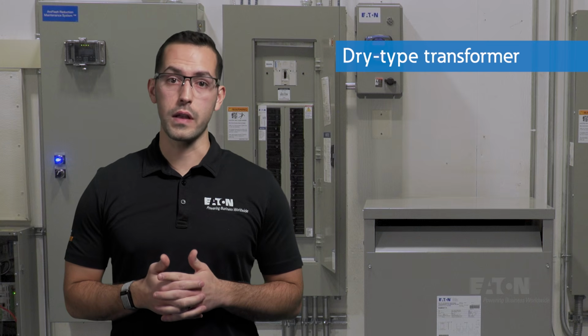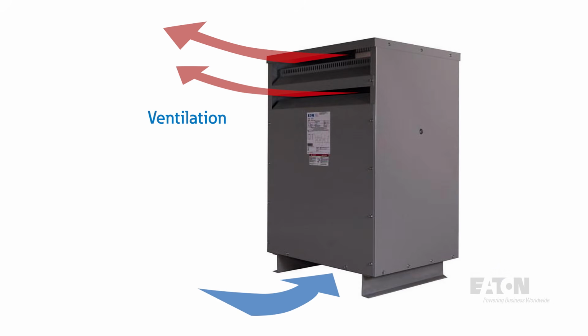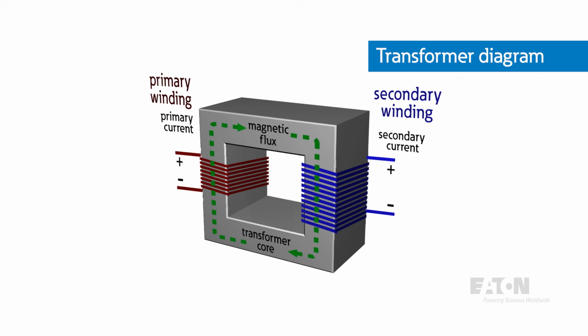With a dry-type transformer, the coils are constructed in a gaseous or dry insulation medium. Natural or fan-assisted convection of the air through the ventilation openings is used to dissipate heat. While the insulating medium is different, the basic concept of winding conductive material around a core and using a magnetic field and winding ratios to induce a different voltage remains the same.